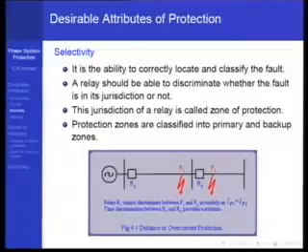So that is one issue. The other issue is that you had two duplicating systems, suppose sharing some common wire or a common LAN cable, or a common DC source which was powering them, and the power failed there, then that common mode failure would affect both of them and therefore they will not operate.